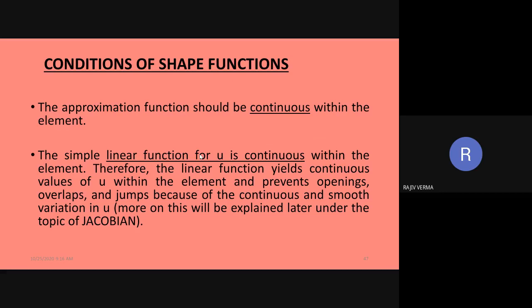Wrinkles basically means overlapping of the domain itself. And opening, obviously, means cracks. So unless you are actually modeling these two phenomena, the entire element is supposed to deform as a continuous member. So obviously a particular mathematical expression which is going to represent this deformation should also be a continuous function.